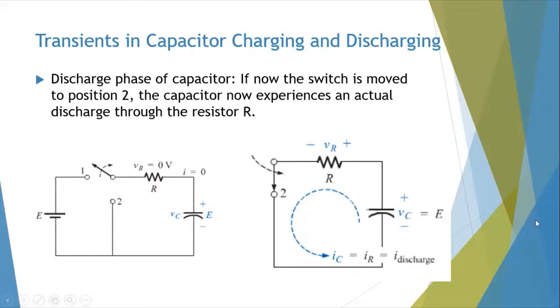So again, same concept we have. You have a time constant now, which is again C times R. Now, your capacitor will start discharging, meaning your voltage would initially be capital E, if it is fully charged initially, and then tend to go to 0. So you can write an expression for VC now because it's decaying. The expression for VC would be the initial value, capital E, multiplied by e to the power minus t over tau. That's the expression for VC when it decays. Now, current initially would be maximum when your capacitor voltage is maximum, but as your capacitor starts discharging, even that would reduce. So both VC and IC would be decaying functions.